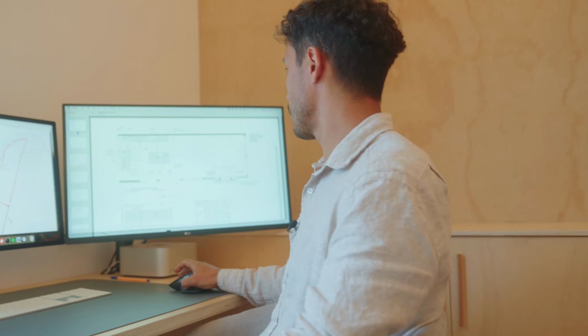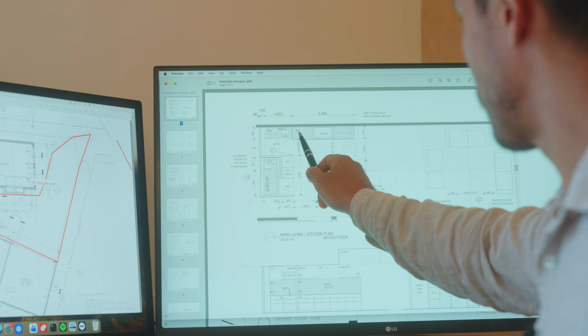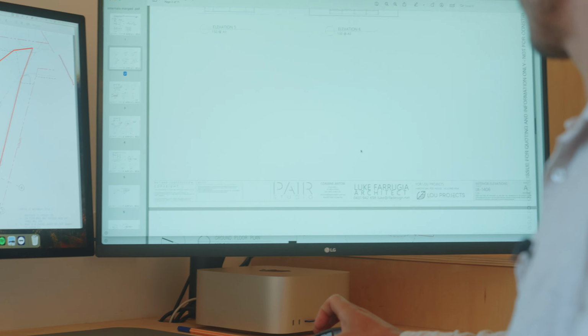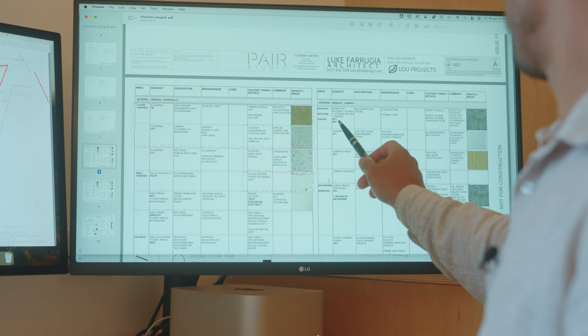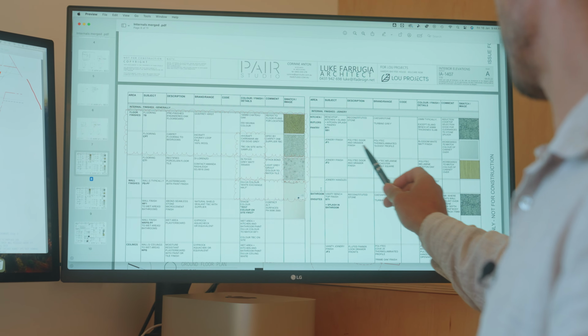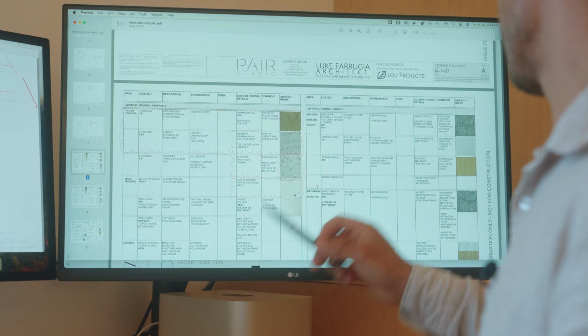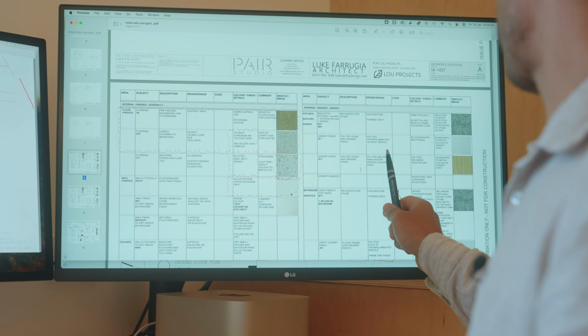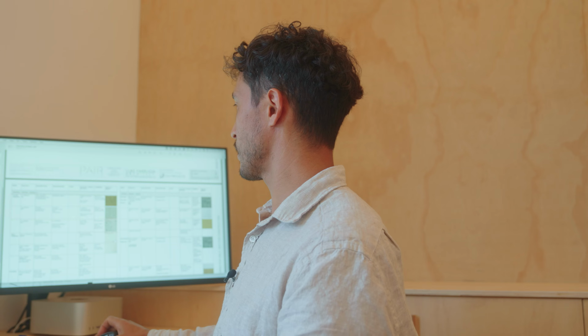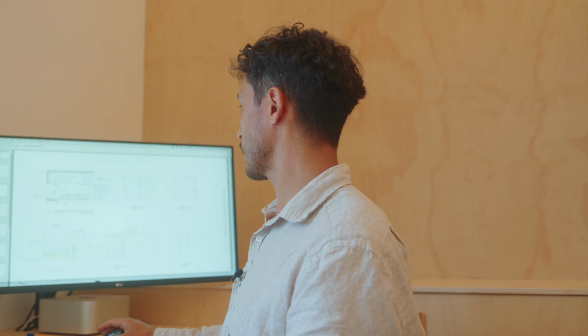So if I refer to those finishes, BT1 and JF2 and JF1, we go down to the finishes schedule. BT1 is Caesarstone Turbine Grey, JF1 is Polytec thermo-laminated, JF2 is Polytec melamine. So when we send this out to our contractors, they just refer to this schedule and they understand what it all looks like.